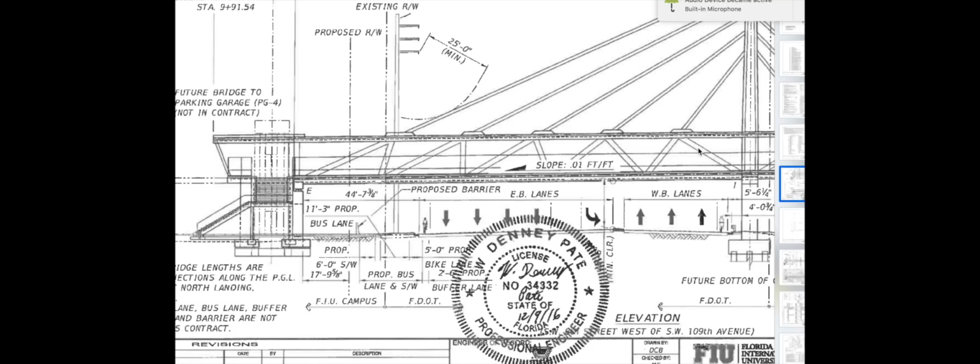This person wrote the report and also told the truth in the report, saying there are no other cracks similar to that on their other truss members. He didn't just say there are no other cracks. So that means there are other cracks on these other members. So they suffered a moment, a deflection of some type.